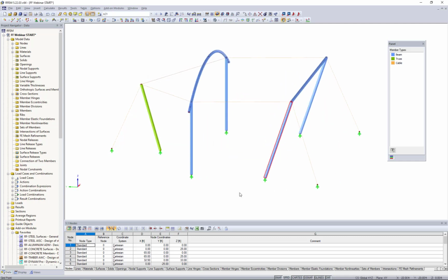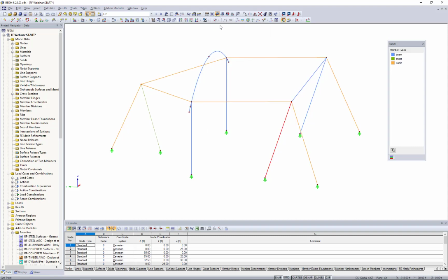What else we have in the model, which is a little bit difficult for you to see, are cable elements. If I turn this into a wireframe view, you might be able to see those a little bit better with this orange color. These cable elements are going to be required to essentially hold up these frames before we have even applied the fabric membranes to the structure. And this is true out in the field as well. They provide stability for our columns and our center frames here.